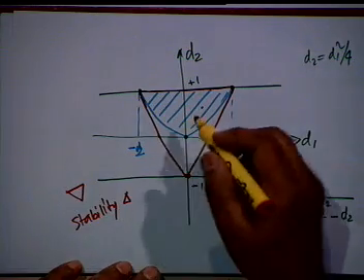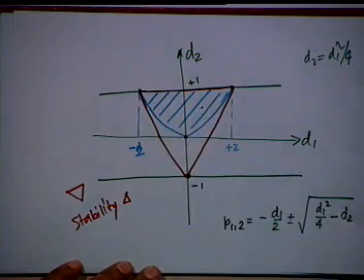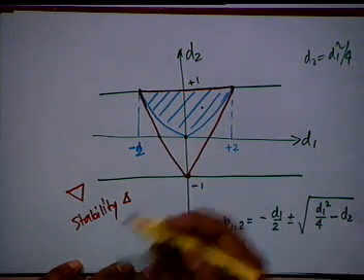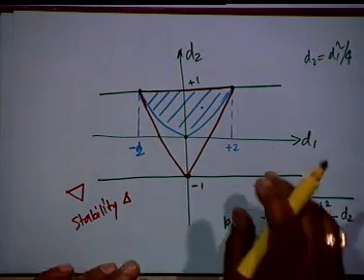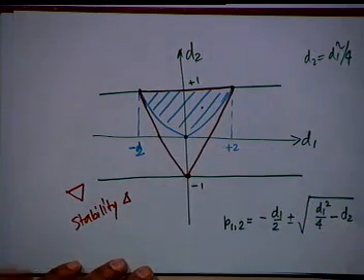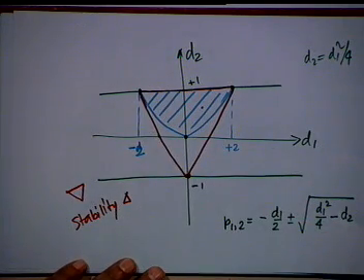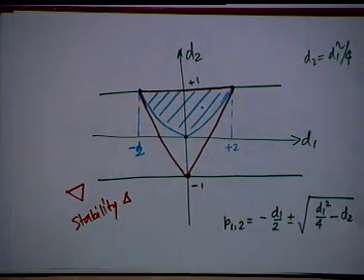In addition, if it is within the hatched area, then the poles will be complex. If not, then they shall be real. If the d1, d2 point is outside this triangle, the system would be unstable. But this is doing too much with a very simple second order transfer function.